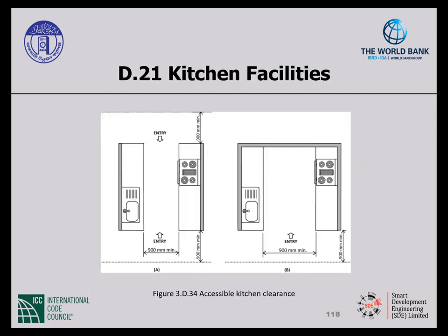Kitchen facilities in residential occupancies should be accessible, and here is how you do that. There's one of two layouts. You can either go with the open layout on the left or the closed layout on the right. The open is like a pass-through, provide a clear aisle of 1015 millimeters. The closed layout, or a U-shaped layout, need to provide 1,525 millimeters between cabinets, and that's due to turning a wheelchair. For appliances, you need to be clearly approachable from either the front or the parallel.